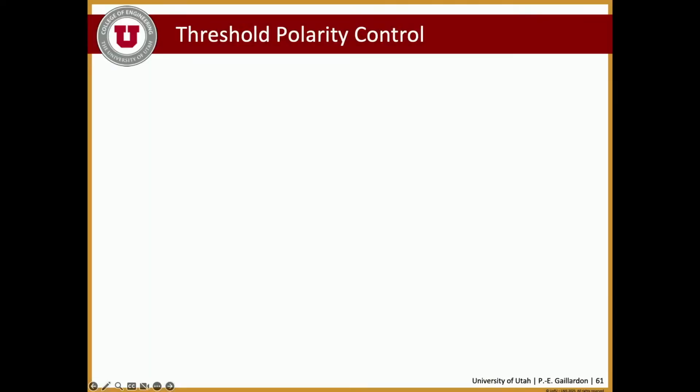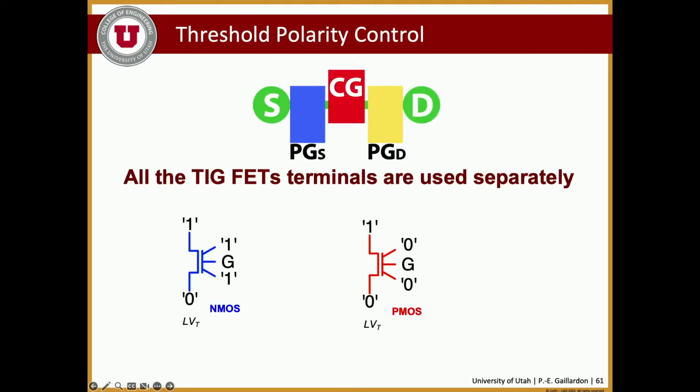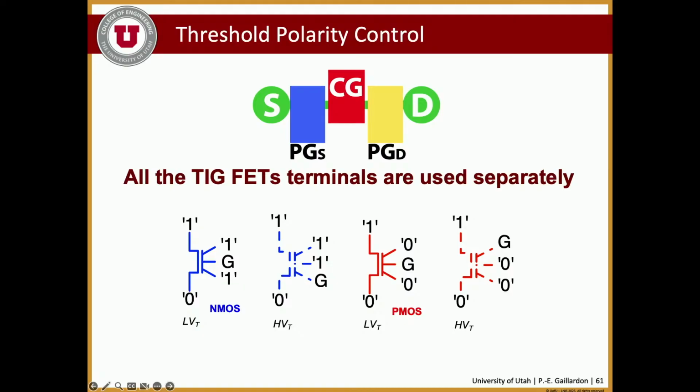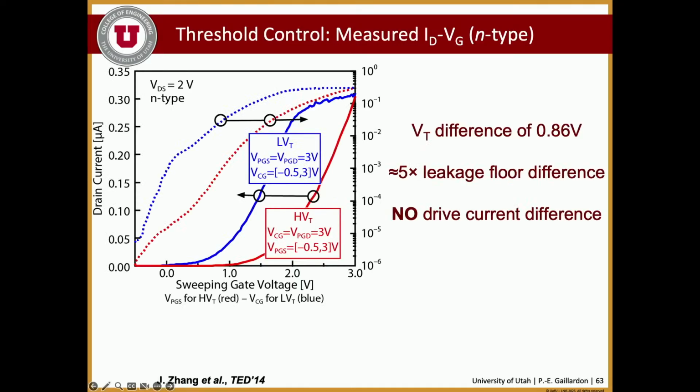Another type of functionality that we have been able to achieve with these transistors is, in lieu of controlling my two polarity gates together, I can have different modes where I'm going to move my control gate to different terminals. So now, essentially, I can use my control signal to pilot the Schottky barriers or the control gate. And that will change the device properties, especially the on and off current that you can achieve and that kind of stuff.